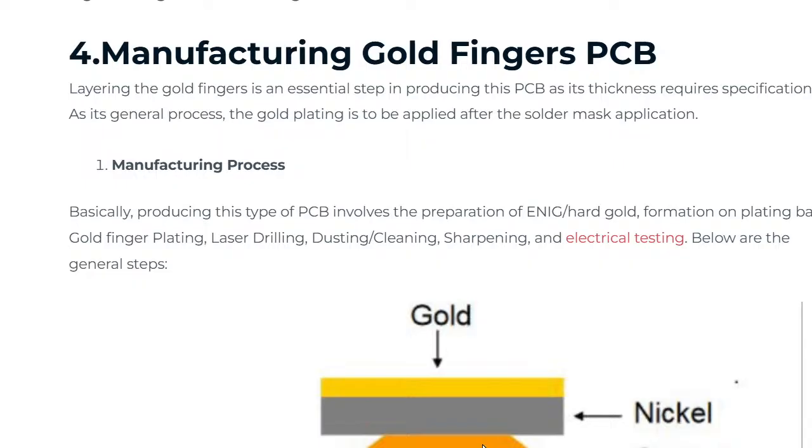You know how these copper tracks are made, right? We discussed the procedure, the etching, the chemistry behind etching, and how these copper tracks are formed. First, they apply photoresist, exposure to UV, isn't it? Dissolution of unnecessary copper, which we call the etching process. So above these copper tracks is nickel, and above the nickel, gold is plated.